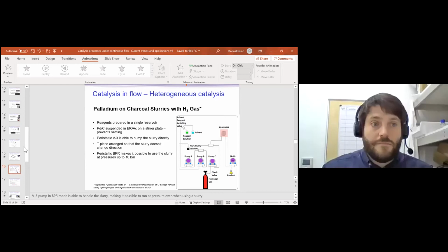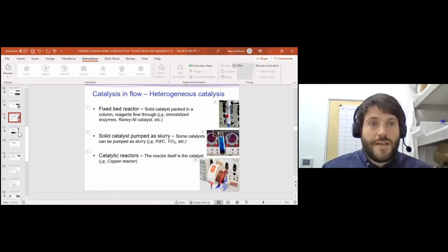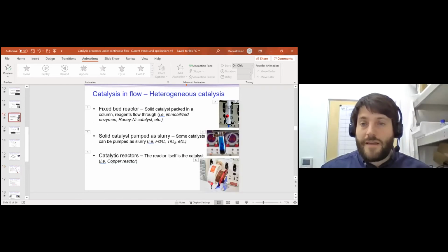Yep. So yeah, we do. This type of packed bed or fixed bed reactor comes in different sizes. We can use a standard small 2 millimeter internal diameter, which is a few milliliters, or we can go to a really big one, which is 15 millimeters internal diameter, and I think it's 4 or 5 times the volume. So yes, we can use a highly dispersed catalyst, and effectively we just need a bigger reactor to accommodate the same loading if we want to compare in that way.